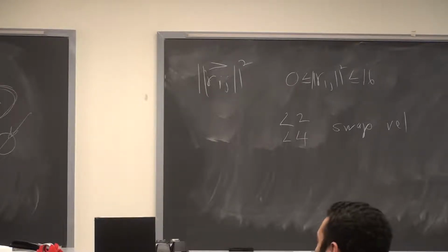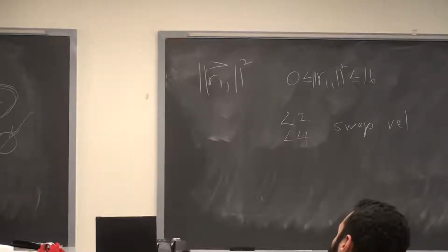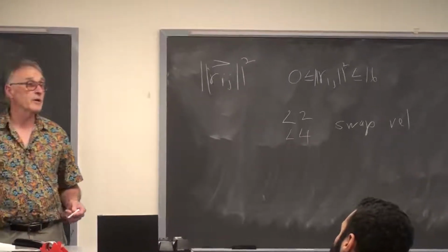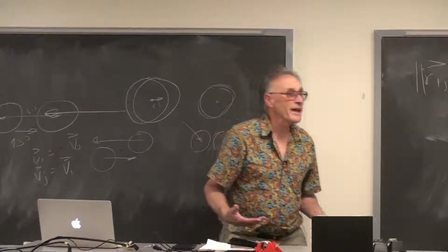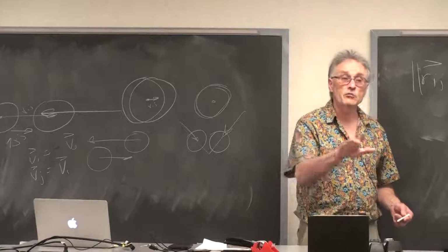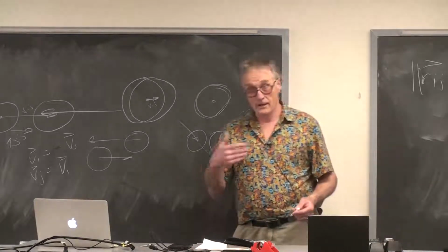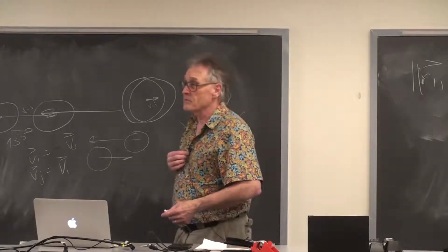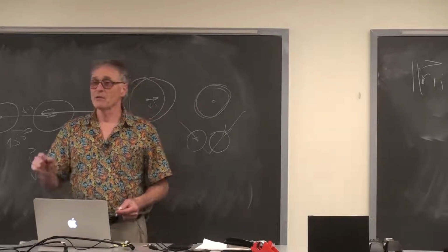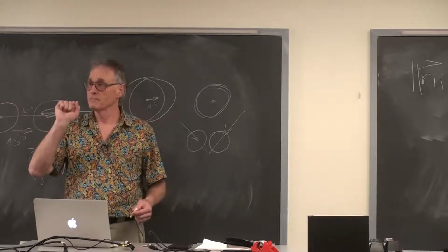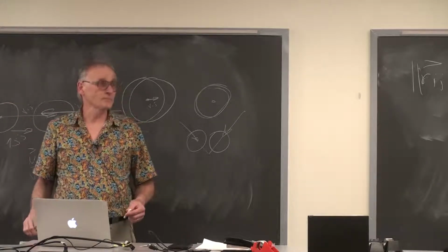So what this architecture does is notice you divided by 0 and throws a software exception. It throws a software interrupt, which is referred to as an exception. There is no exception handler written for divide by 0 unless you write it. You haven't written it, and neither have I. Therefore, the system takes a reset. And so the symptom of a divide by 0 will be a flashing TFT display. That's obscure.